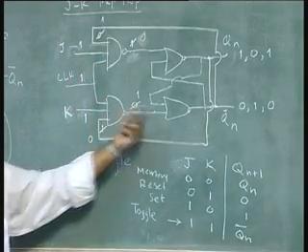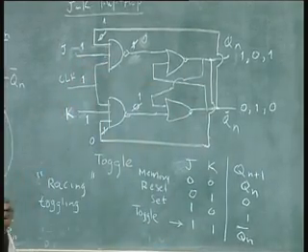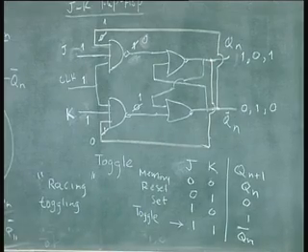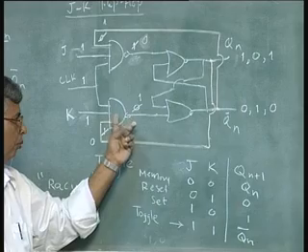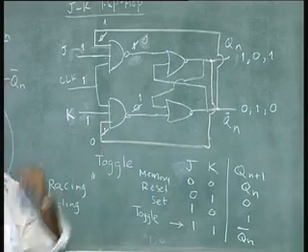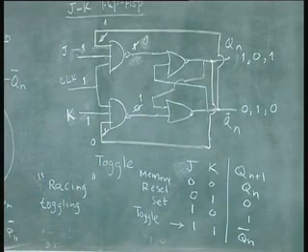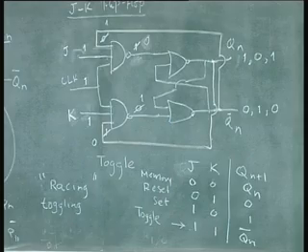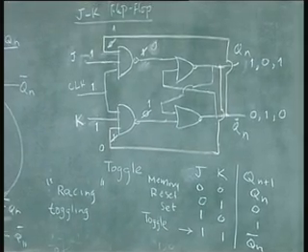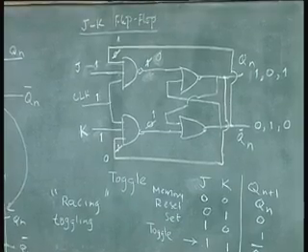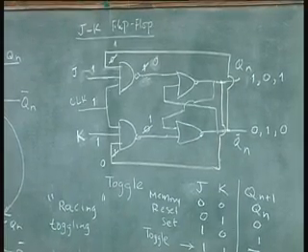At the end of this period, it goes back. So, this toggle time is determined by the delay of the two gates. It will be very, very small, especially with modern day gates, where the delays are of the nanosecond order, whereas we can never have a clock of width less than that.